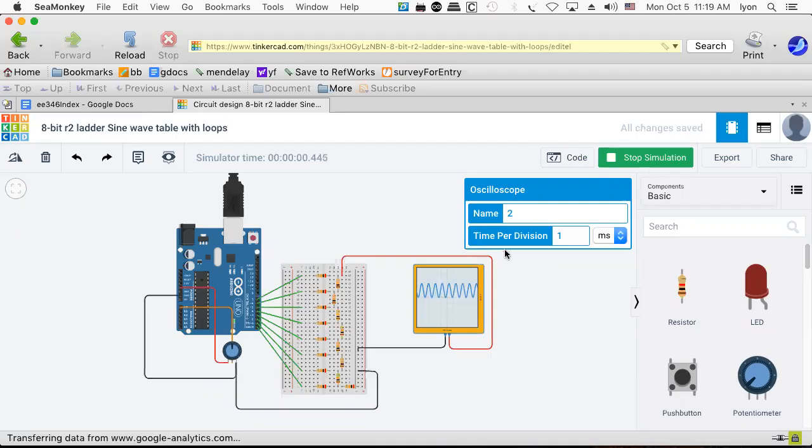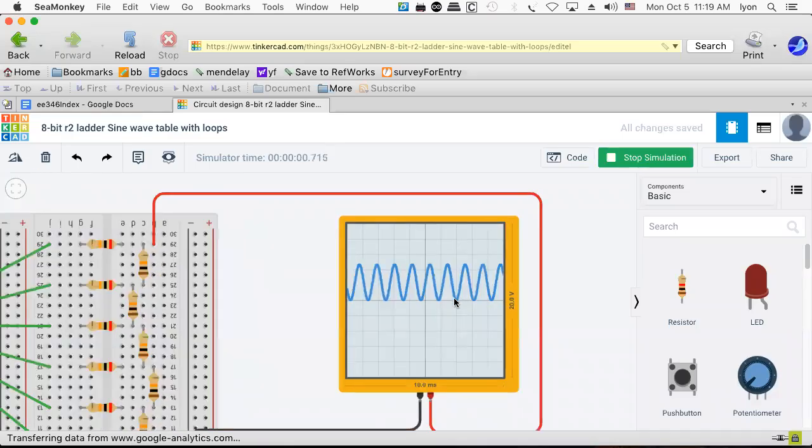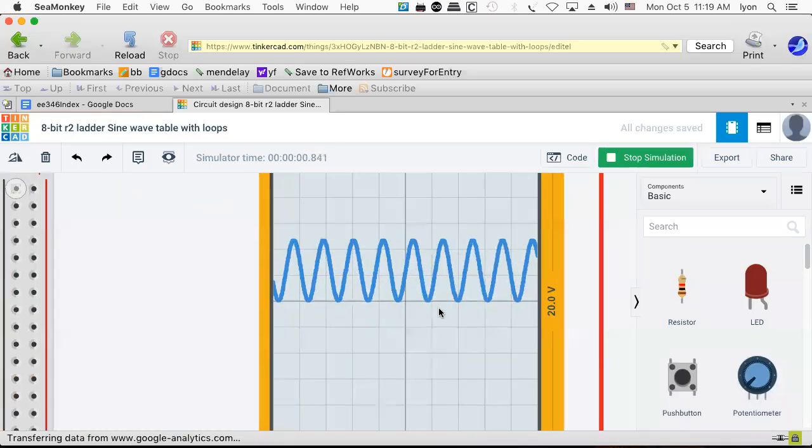So if that's really 1 millisecond, then in theory, you can look at this waveform here, and you can say, hey, wait a minute. Here's a trough, and there's a trough. This is 1 millisecond per division, so this is a little bit lower than a kilohertz, right? Because 1 millisecond is 1/1000th of a second, and so that's like a 1 kilohertz waveform. And there you have it, right? You've measured the frequency, such as it is.